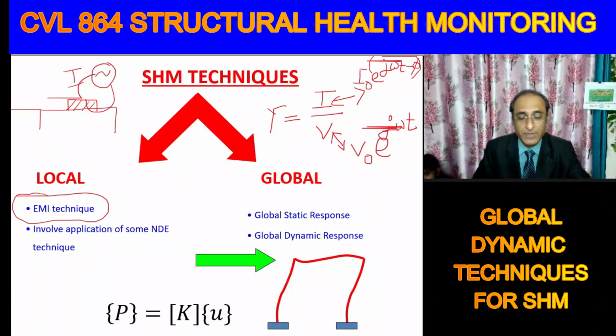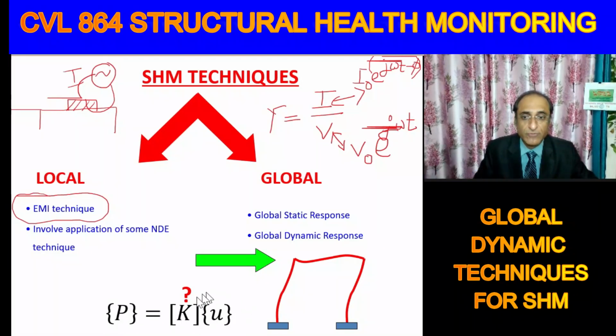deflections. Now we have learned from our structural analysis 1 that the loads and the displacements are related by the stiffness matrix. So essentially from the input and the output, input meaning the force applied, output meaning the displacements, we have to obtain the unknown stiffness matrix. That is the working principle of the global static techniques, and it is practically very tough. Theoretically it looks very feasible that if we have the output input pair, we should be able to derive the stiffness matrix very easily, but it's not that easy, especially the execution of the experiment itself is very tough.